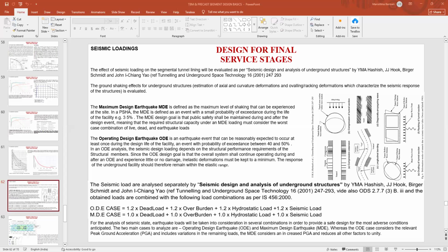So if you are designing a structure for 10 rupees, but your original design is valid for 25 rupees because 2.5 times you have taken as additional load, that is why the structure will not collapse. That is why any non-engineering person will always ask you, whatever you have designed, can you ensure the structure will not collapse? You can ensure it if your partial factor of safety has been taken.